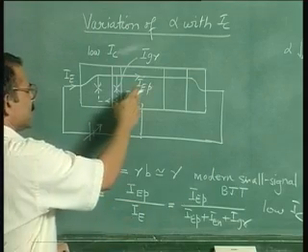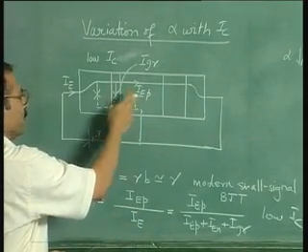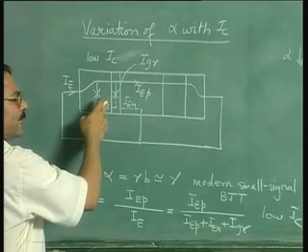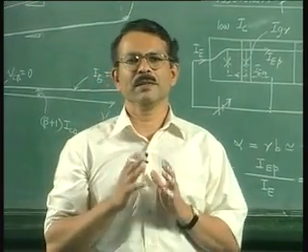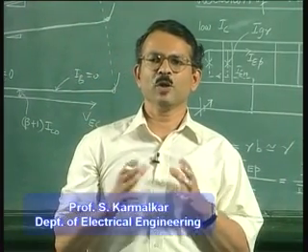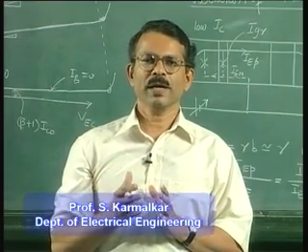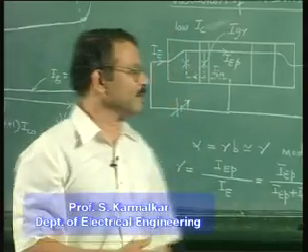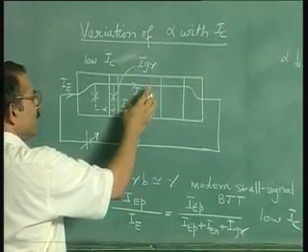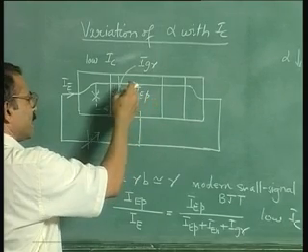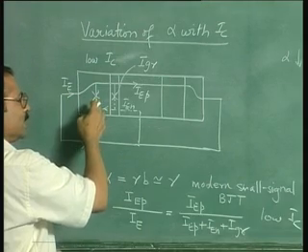When the injection level in the base is high, the amount of electron current that is injected from the base to the emitter is more than what you calculate assuming low injection level in the base. This follows directly from the Boltzmann relation. From P-N junction theory you can easily show that when one region of the junction is in high injection level, the amount of current that this region injects into the low injection level region is higher.